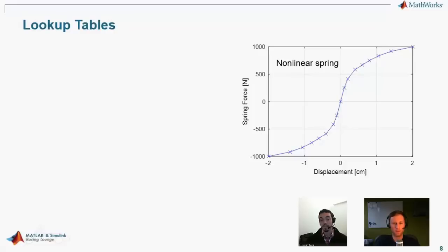So yeah, it's great because in this case you don't have to create equations for your system. By collecting such data, you can have a simulation where, let's say your displacement is 1 centimeter, you can simply draw a line upwards here and then trace it to the location over there, and then say, if my displacement is 1 centimeter, I should expect a force of maybe 800 newtons or so. So it's a good way of introducing small components that have a very simple input-output relationship.